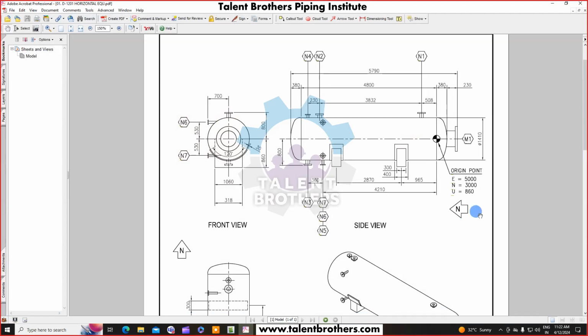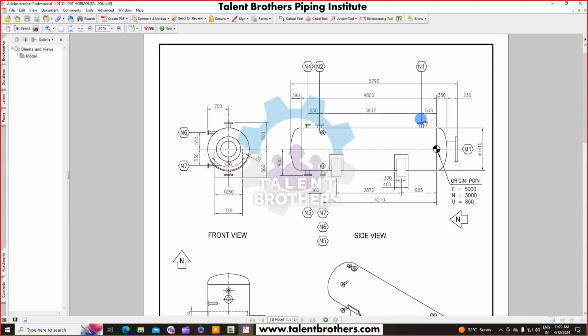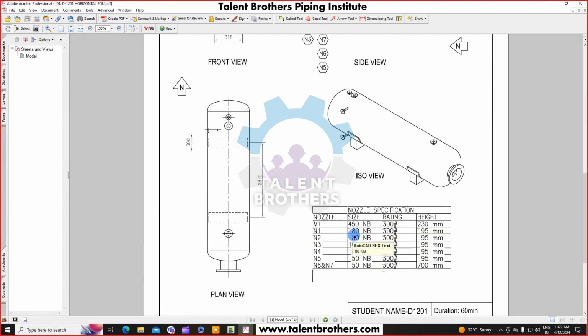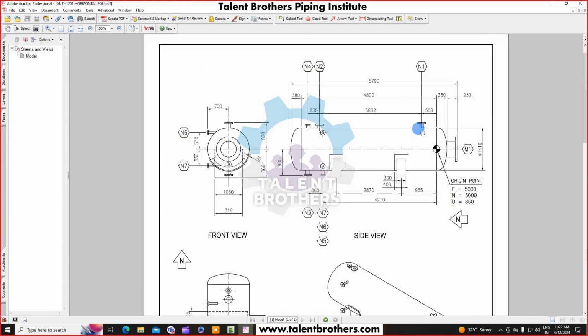Okay, and parallelly you can use the copy paste command here and there, and then nozzle 2 is here. Nozzle 2 is the same, everything is the same, size and bore also everything the same. The only thing is the offset, the copy offset is 3832.